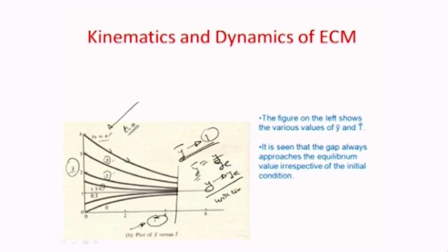Okay. So if you look at this paradigm, you can always see clearly that ECM, or electrochemical machining, is a sort of equilibrating process, and the perturbations on a surface, or the roughness of the surface, really are leveled to a point when the value of y becomes equal to, be it whatever gap to start with, at a certain time scale or time ratio, the equilibrium gap.